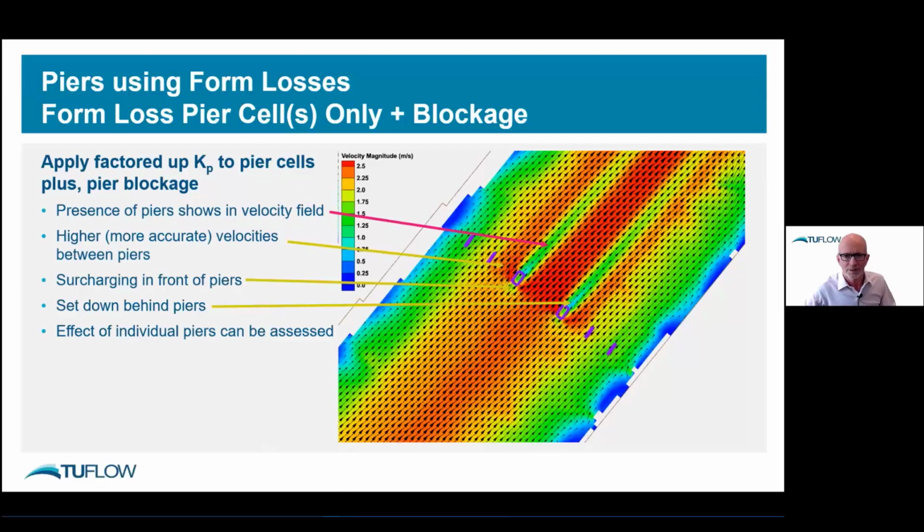Let's add some blockage. If you add the pier blockage to that simulation, you just see a stronger wake behind. You actually even start seeing surcharging in front of the piers because there's blockage applied to those cells. And yeah, that also gives quite nice looking results.